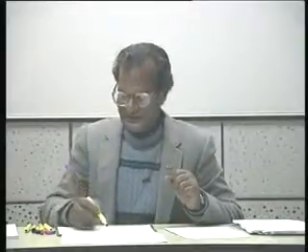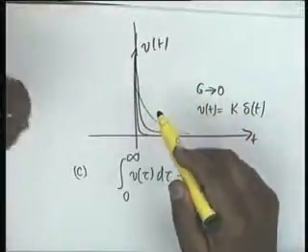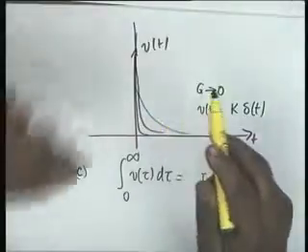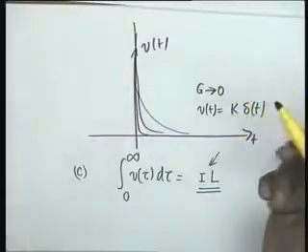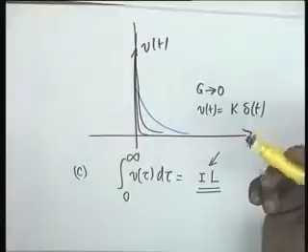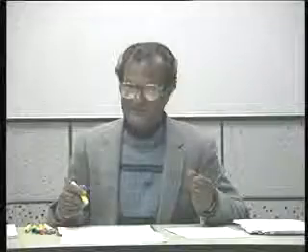That is what you have shown. No, sir, from the expression, the area under the curve is constant. Don't we need to show that when G tends to 0, this whole area is present at t equal to 0, because the time constant capital T is 0? So in 0 time it falls to 1 by E of its value. In 0 time it falls to 0 of its value also. There is nothing sacred about 1 by E. It could be 1 by 100, it could be 1 by 200, or it could be 1 by infinity even then. But I agree, it is still a physical argument.